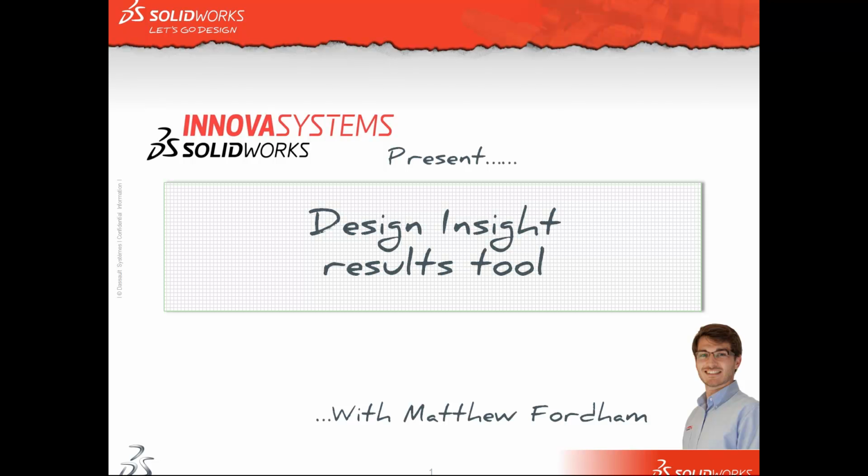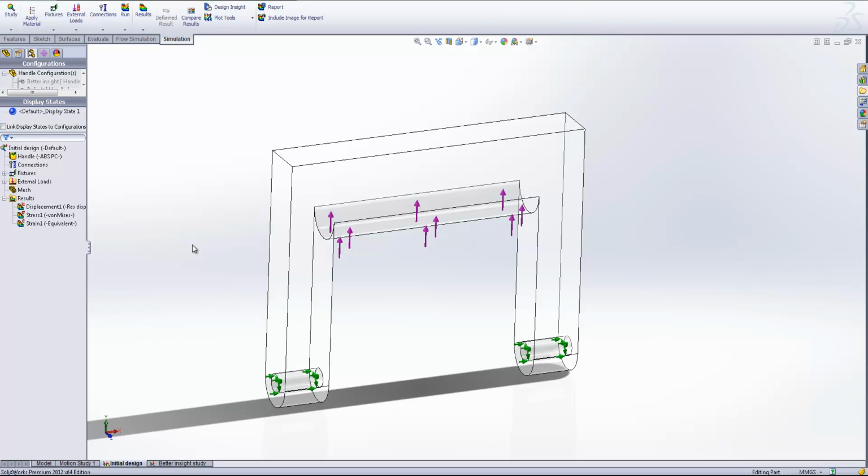My name is Matthew, and this time I'm going to show you how to use the Design Insight Results tool in SolidWorks simulation. Okay, so what you see on my screen now is a very simple model of a handle. I've got a fixture applied to these two internal cylindrical faces here, and a pulling or tensile load being applied to the face here, which is where we're going to assume that our hand is pulling. I've already run the analysis and I've already got some stress results, so let's have a look at